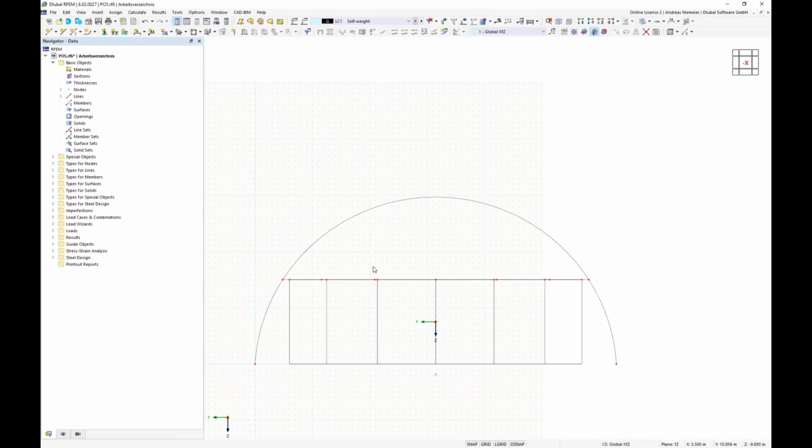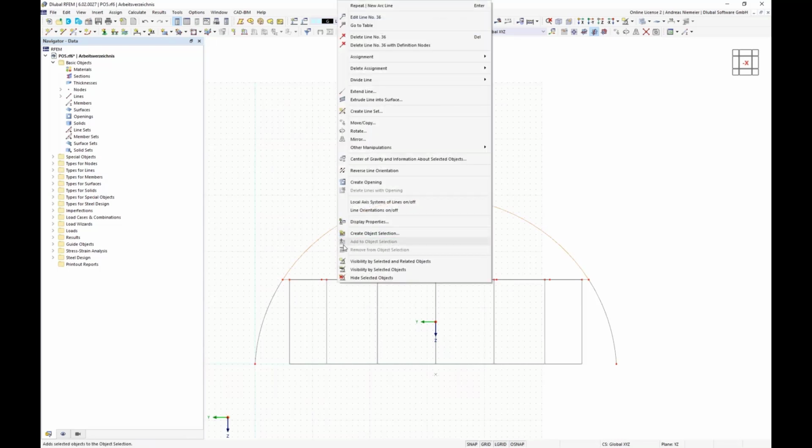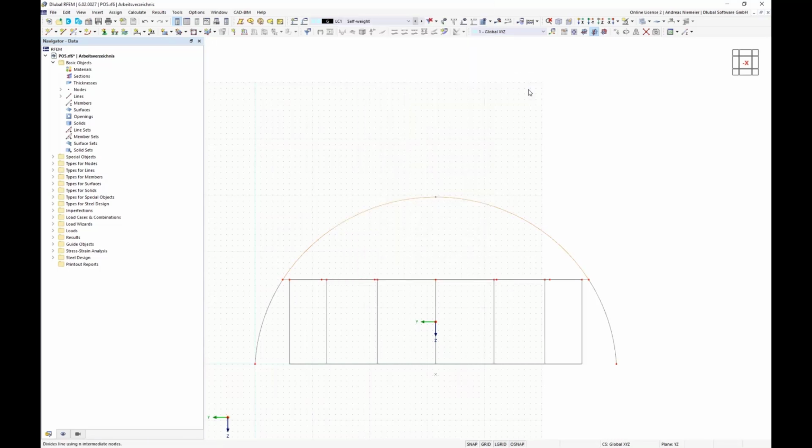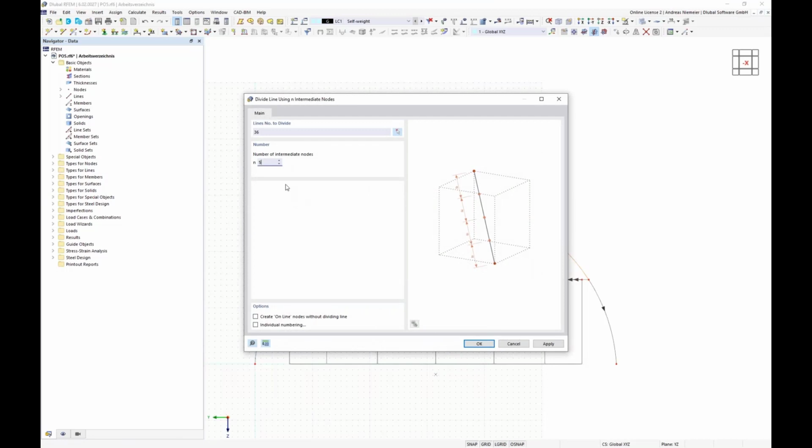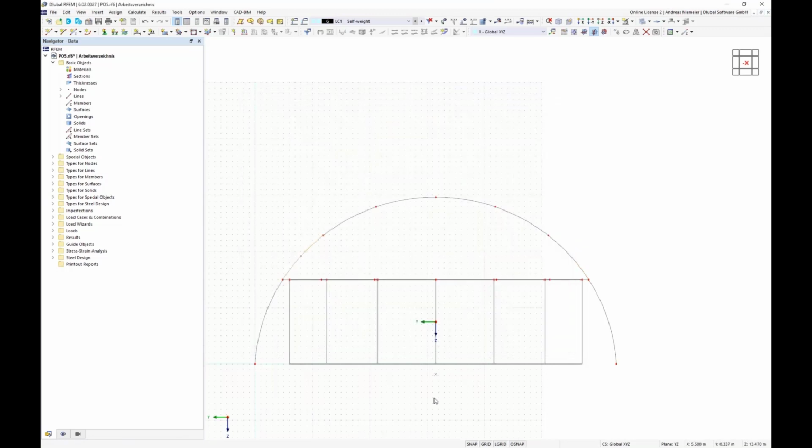And with seeing this, we have to go away from this circle definition. We need something more general. So here I recommend to work with splines. And to work with splines, we need some control points. And for this, I take this upper arc part and divide it in, let's say, parts, for example, in 5 elements here.